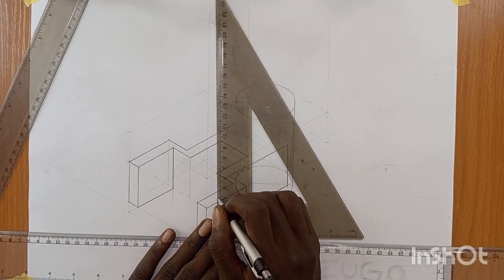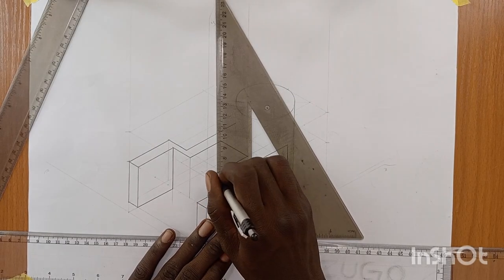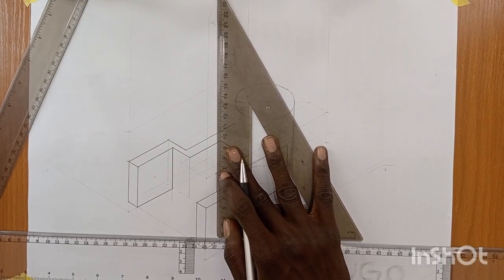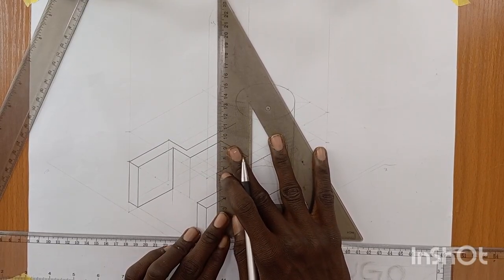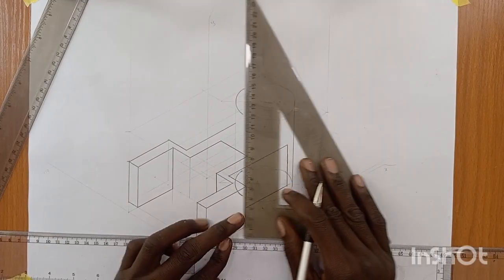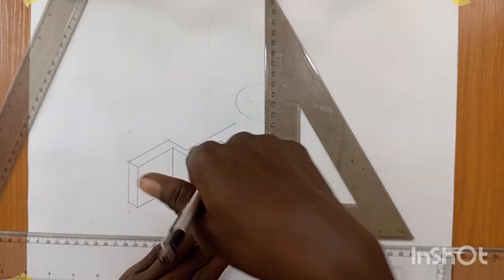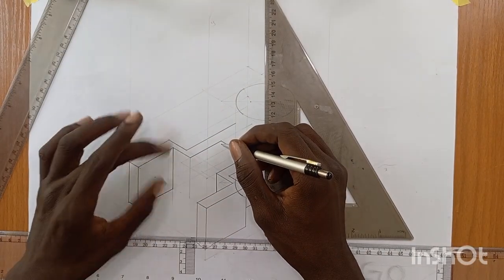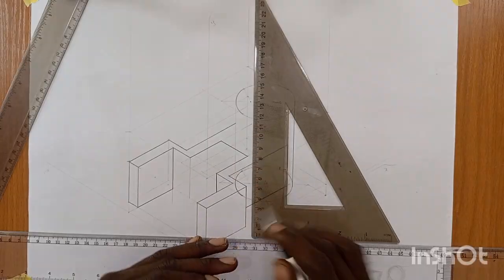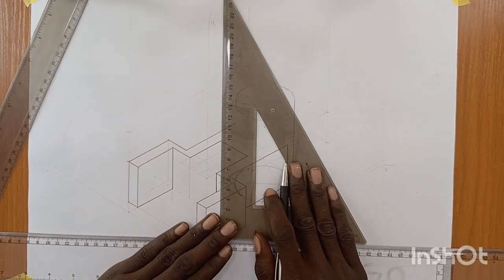But since this drawing here is blocking it, I want to make a bold line. Wherever it touches it, we stop there. The other line cannot be seen because it's being blocked. So now we draw a vertical line downward here, and we stop here. That is it. Also, this line from inside goes downward the same height of 40 millimeter. But this line to here is less than 40. We just draw the line vertically downward to connect them.